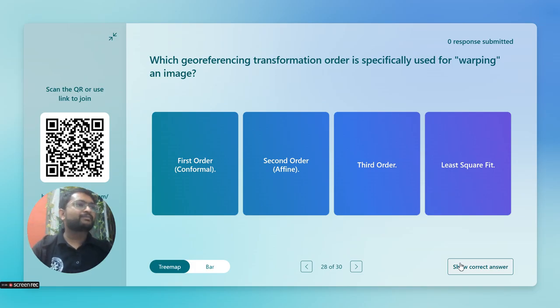And why will that happen? Someone told that it can be because of the curved nature of the earth, or we had some curvature corrections, or it got literally warped while collecting the image. And sometimes when we do the transformation from one coordinate system to another, in which we are showing the curvature of the earth, during that time also this warping will appear. The sensor angle will also lead to warping. Yes, exactly. So angular effect also will lead to warping. Yeah, true.